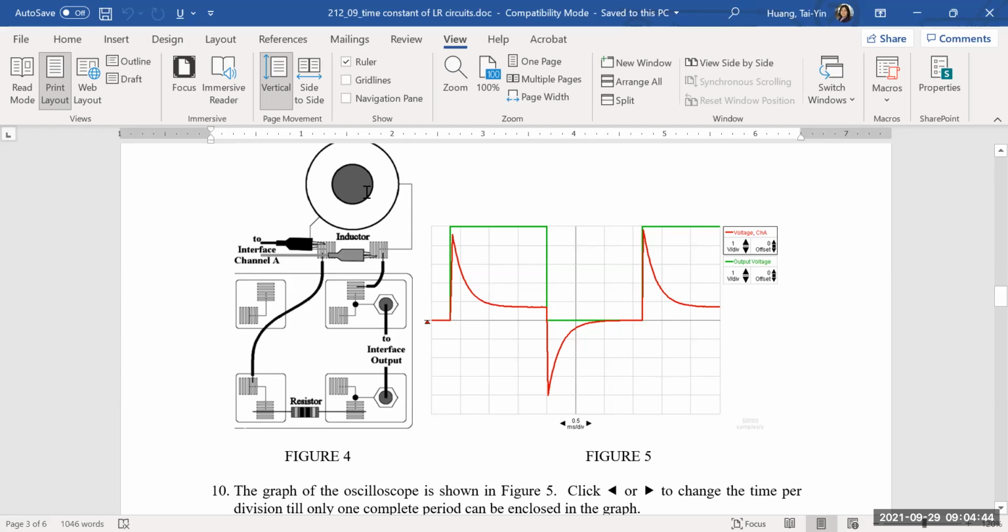So we're going to have 2 scenarios. One is just the inductor itself, and the second is that we're going to put an iron core inside the hole of the inductor to enhance the inductance value. So you're going to measure the inductance of the inductor with and without the iron core. You'll find that the values will be different, because even though you're measuring the same inductor, the material inside the hole will change the inductance value.